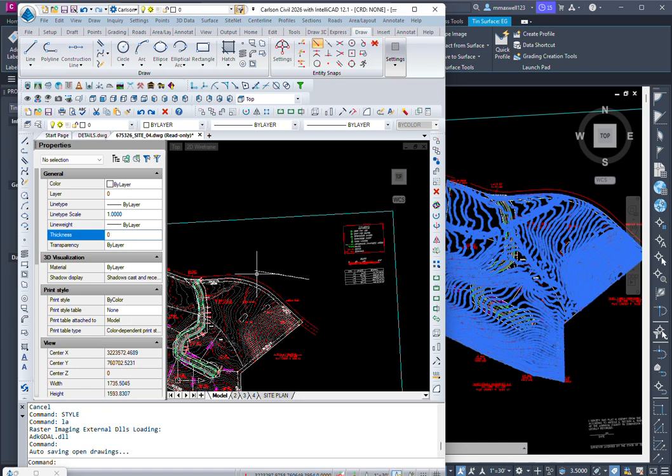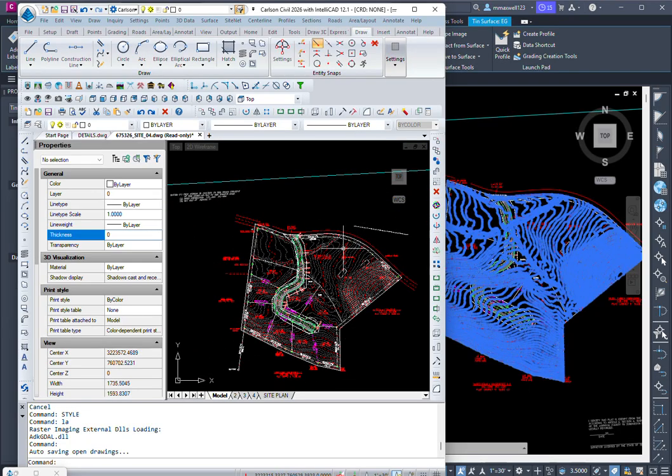Hope this helps. This is pretty critical. And when I would train people, this was the first day training. If you don't have this set up this way, you'll have issues in Civil 3D with labels not showing up in model space, plots that look one way on the screen but plot a different way. This generates most of the issues with working with CAD until you get into the more advanced stuff.